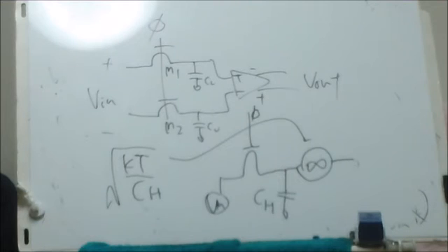As mentioned above, the MOSFET is thought of as a resistor. And so kT over C noise in the circuit is from MOSFET thermal noise. If we review the noise mechanism found in MOSFET in chapter 9, we'll also see that flicker noise may be present. However, for MOSFET's drain current to contain flicker noise, the MOSFET must be conducting a DC current. Because the MOSFET in figure 7 doesn't conduct any DC current after CH is charged, flicker noise doesn't affect the sample voltage.